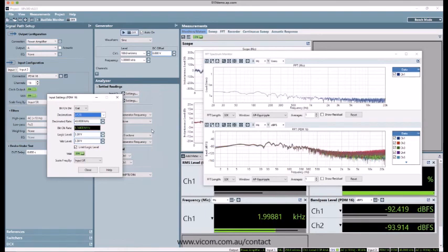and we have a mathematical algorithm, a set of feedback and feed-forward loops that push the quantization noise produced by that up above the frequency range of interest, or the audio band, for our applications. So there's a bunch of energy up above 20 kilohertz.